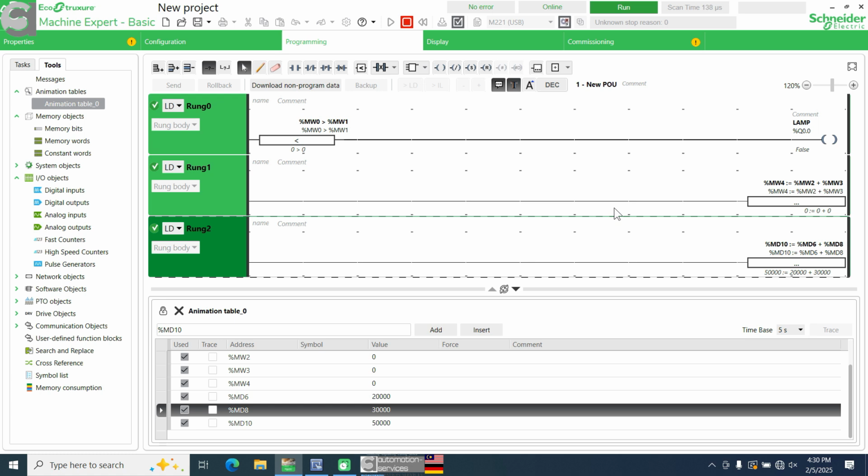Once the temperature inside reaches 80, this is where we use the compare function. Comparison of your set point and your temperature. If the temperature is more than or equal to your set point, then you turn off the output, then the heating coil will turn off. The temperature will go up a bit, 81, 82, 83, then since this one is already off, it goes down.